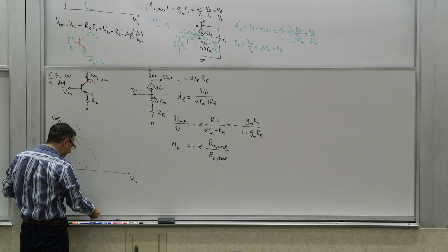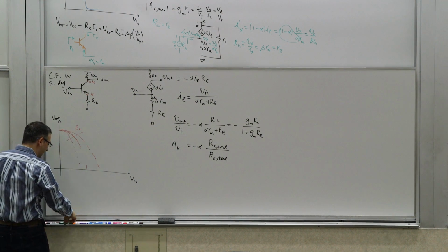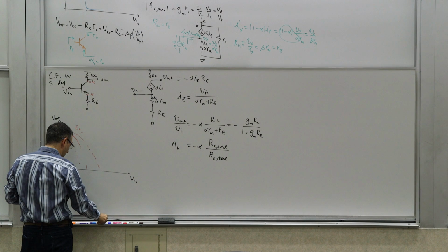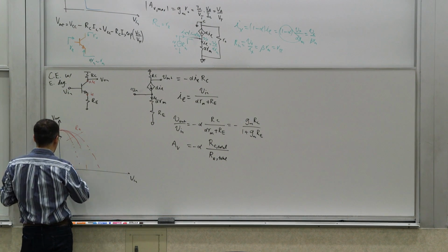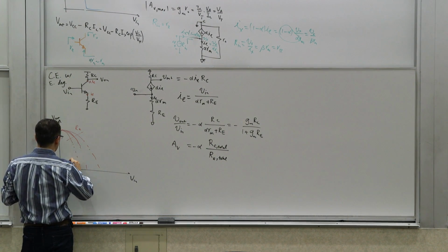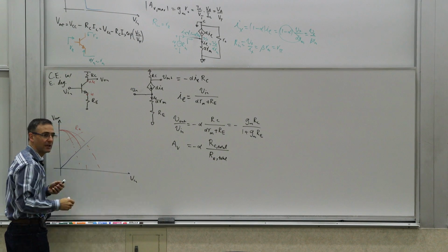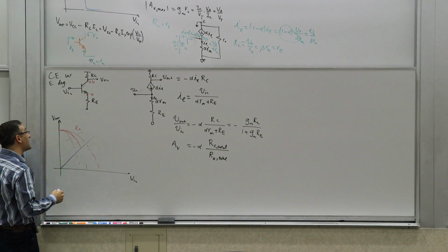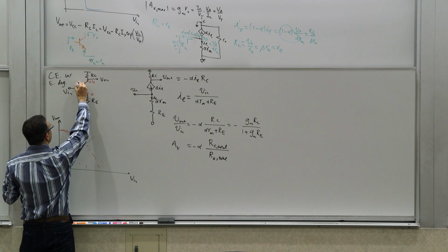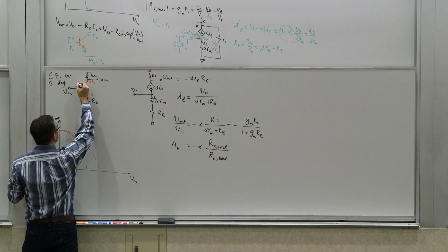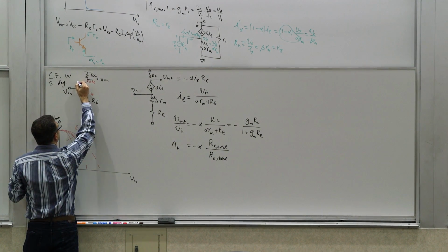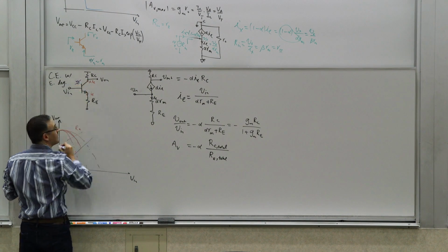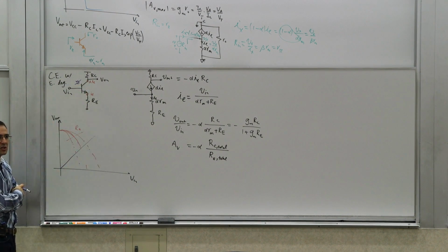But if you look at the input voltage, which is the base voltage, that voltage is actually going up, right? So that is essentially this voltage. It's going up. It's Vn. So at some point, right? So think about it. There is a diode here, right? This is an NPN transistor, so it basically means that it's like this. There's a PN junction diode.